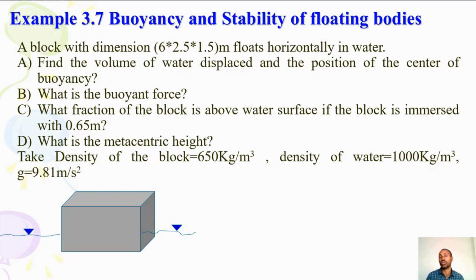The material should have little or no tendency to absorb the fluid, and also compatibility with the fluid in which it will operate. It should also have an ability to be formed to appropriate shapes, an ability to withstand the fluid pressure to which it will be subjected, and also abrasion resistance and damage tolerance.